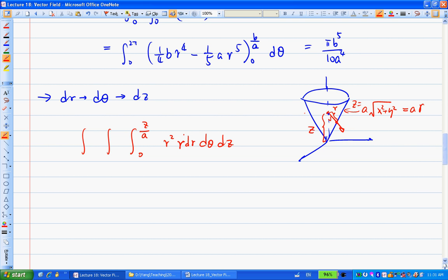However, there is a case where it's going to be 0. That's when you have a very thin cylindrical bar. Let's say for example this pen here. If you consider this pen as a very, very thin circular bar, then the moment of inertia about this z-axis, which is the axis going through the cylindrical object, you consider as 0. Basically the r, the distance, you consider it as the cross-section is so small.